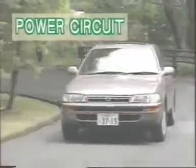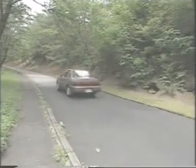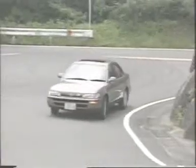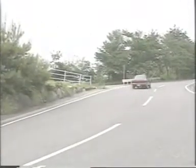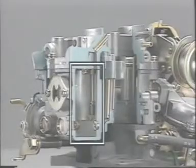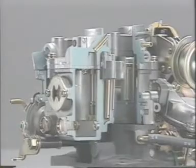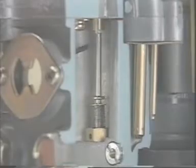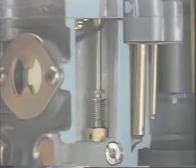Now let's take a look at the power circuit. The high-speed function provides insufficient fuel when climbing steep grades or when extra power is necessary. This is where the power circuit comes into the picture. The power circuit consists of a power valve set into the route that communicates with the primary main jet. It opens to allow more fuel to flow through to provide the rich mixture needed when extra power is called for.